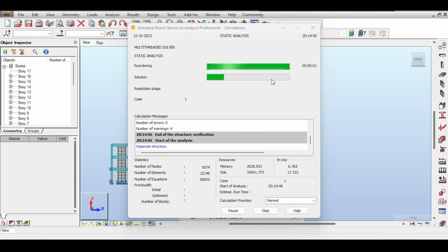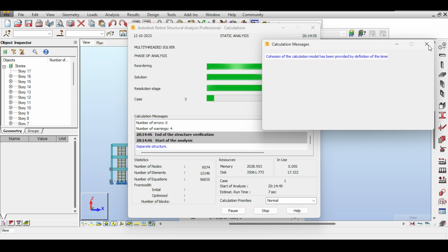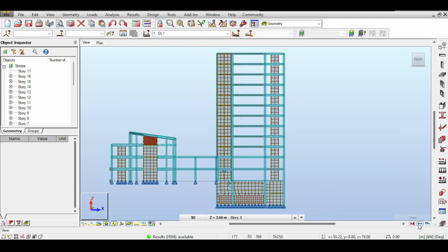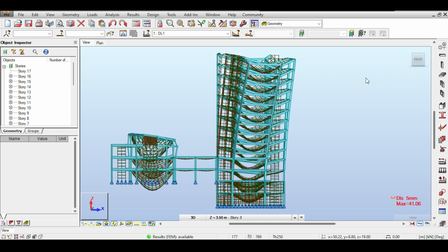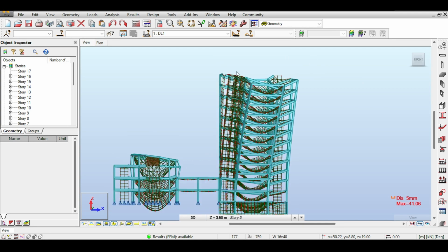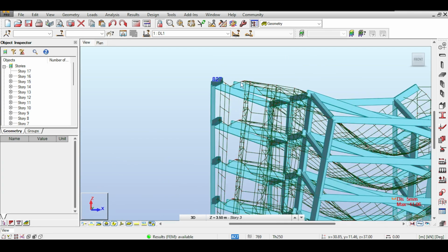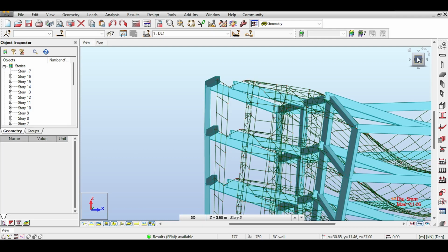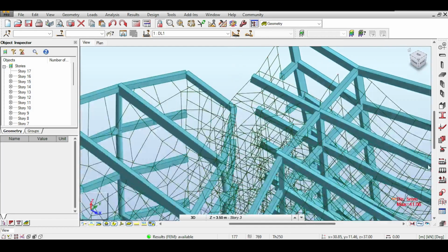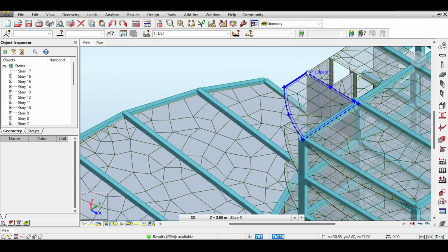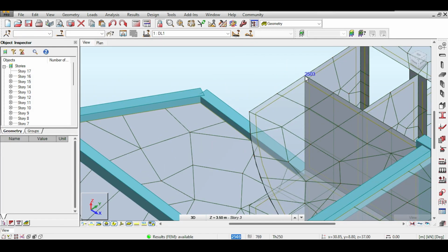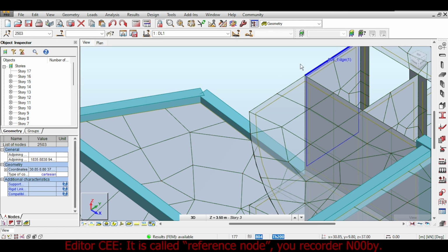Now, as I said before, I went through most of the warnings you will see here, so I will not address them. There is no error. Those are warnings I have talked about in the previous videos, so I will leave it as is. And now let's just open the deflection and take a look at the deflections. So, okay, fine. Let's now go to top, maybe, and just remove the deflection and select this node so that it is going to be our benchmark.